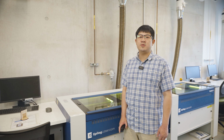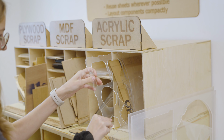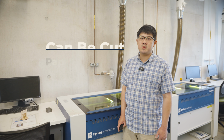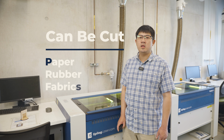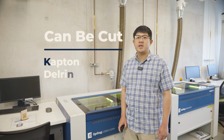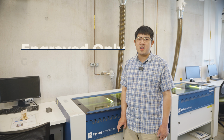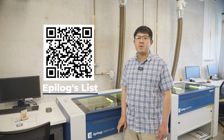The most common materials to cut and engrave on the laser cutters are wood and acrylic, also known as plexiglass. Many types of paper, rubber, and fabrics can be cut, along with engineering plastics like Kapton and Delrin. There are also some materials that can be engraved but not cut, such as glass and stone. A full list can be found on Epilog's website, or you can ask a staff member if you have questions on material choices.